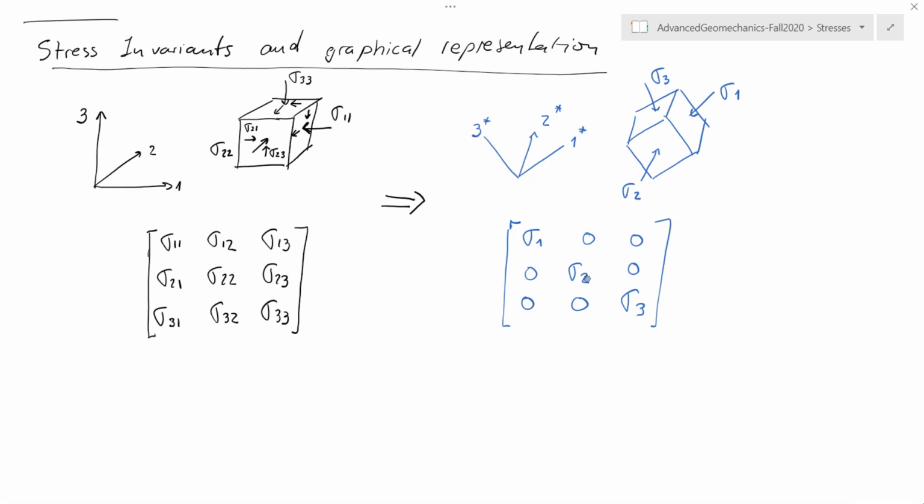For example, instead of plotting the entire stress tensor, you could plot the minimum principal stress, sigma 3. If you do that, for example, in a 2D or in a 3-dimensional space, you could find out which are the points in a solid which are subjected, let's say, to tension, or which are the points that are subjected to a value lower than a tensile strength value. You could do that. And here we're going to see several ways that we can plot the stress tensor in a way that it's easier to understand, at least easier than just looking at the numbers only.